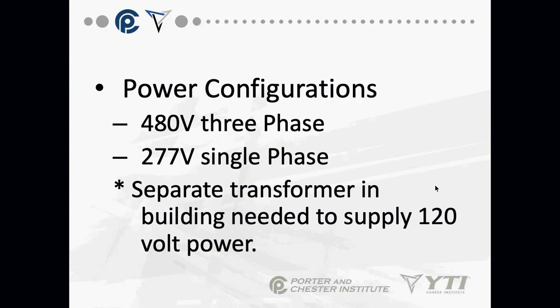I've actually heard that delta is an older thing that you may see, because they've been trying to phase out the deltas. Yes, for the power company to actually reconfigure the larger transformers if they have outages, it's easier for them to work off the Y. That's why I don't want to say never, but I want to say the majority. And I agree with that. The companies are trying to phase out the delta because it is a problem. By the way, that has to be a neat job, going and reconfiguring those transformers.